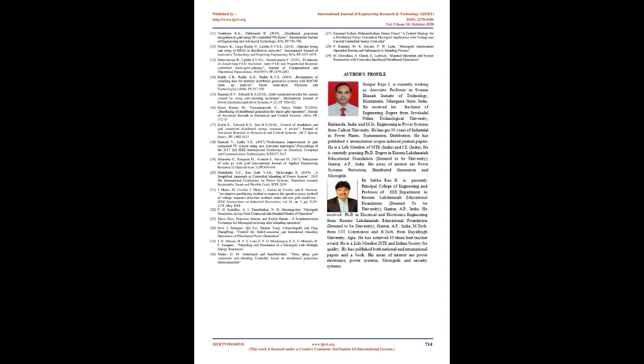The loads and DG are adjusted for zero mismatch active power. The reactive power is adjusted to 0 var. The circuit breaker is operated to create islanding. The worst scenario islanding is simulated and the islanding technique is evaluated. The results discussion. The sample time is 1.5 secs and the number of samples per 50 milliseconds is 1000. The islanding is done at 0.8 secs.